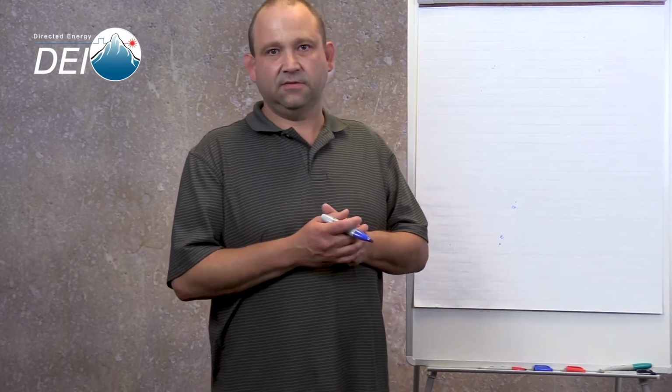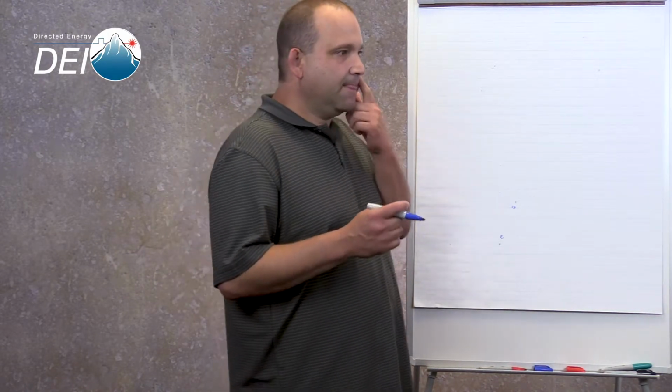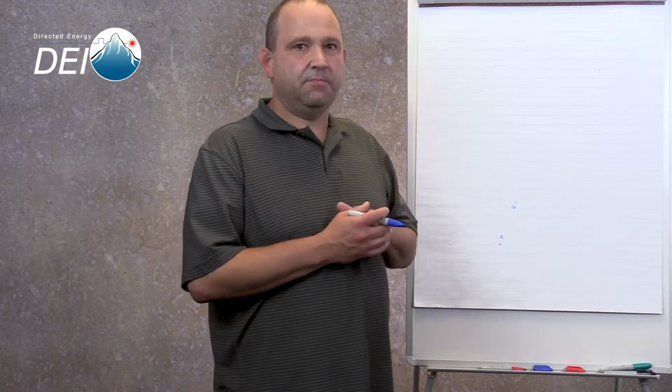So we are going to do an example of determining what the max load capacitance is for your PVX high voltage pulser. In this example I'm going to be using a PVX-4100 using this RG59 coax cable.